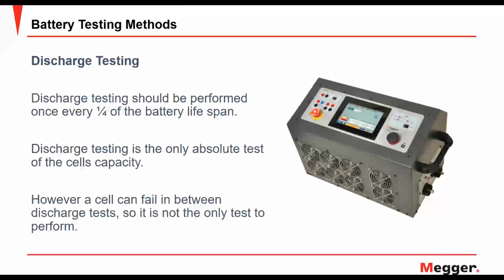You can add it to detect any premature voltage drop in any of the cells during the discharge process, and it can even automatically change or stop the discharge process, indicating that you have found a failure in one of the cells. We have the Torkel 900. It's a very good device to do this test. I urge you to check it out in the data sheets on our website.